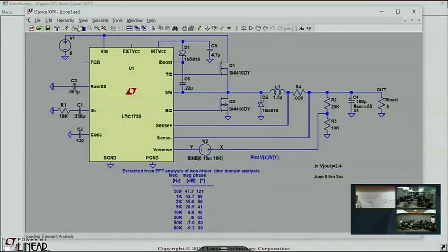Well, if you've got current and you need voltage, you could read it out with a resistor. That would be problematic. In principle, you could get it to work, but let me just cut to the chase. A much better idea would be to read out that current to a voltage with a capacitor. Because if you convert current to voltage with a capacitor, you're going to have a huge gain at DC. And the tightness of regulation of a negative feedback loop increases as the ratio of open loop to closed loop gain increases. That capacitor gives you a huge AVOL, a huge DC gain. And the reason that's a voltage is because that's a capacitor. And that is one more pole.